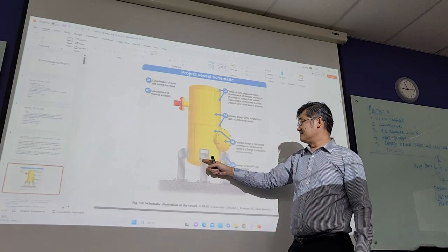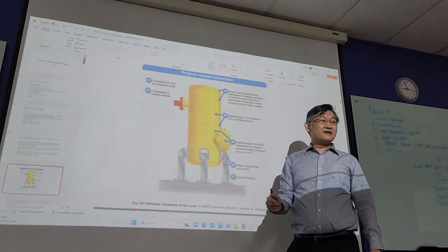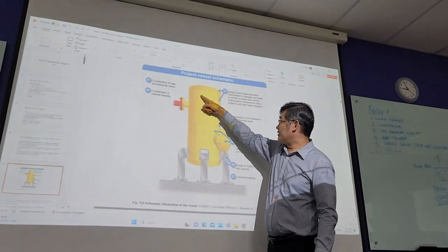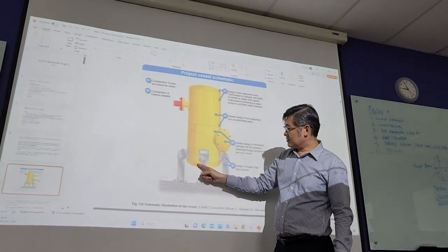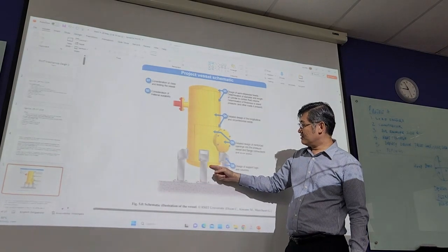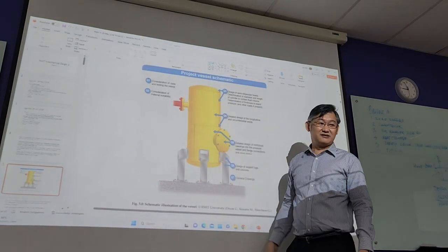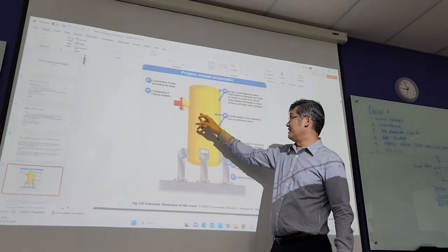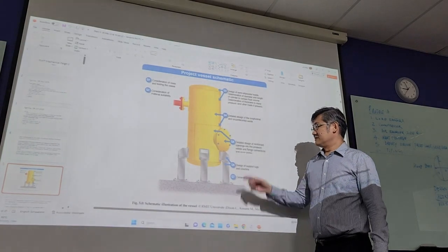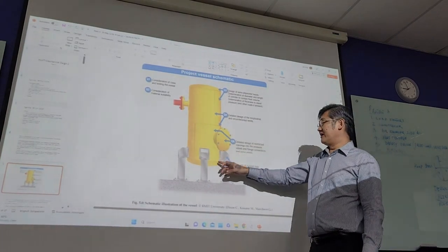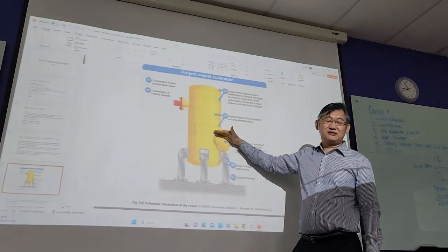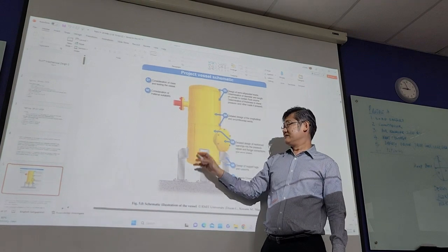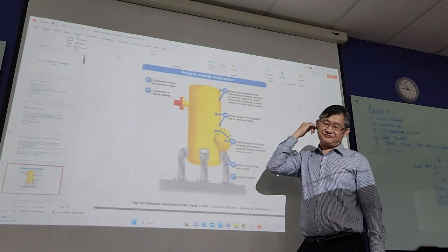But the cylinder is this. So the length of the cylinder, later on you have to find out, is the length of the cylinder, this part. After that you might include the 2 ends of it. So this will be your length of your cylinder. Total length of the cylinder includes this semi-ellipsoidal head. That's why your volume determines the length, the diameter used, and also how we select the semi-ellipsoidal head, depending on the volume that you computed.